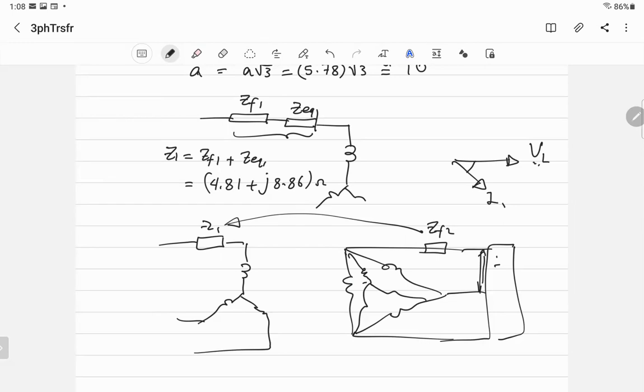Yes, you can take the line voltage and divide by square root of 3 to find the phase, but what about the angle? Is the angle the same? No, there's a shift of 30 degrees, 150 degrees. There are many issues about that. You have the power factor, you have this angle. Usually I make this 0 and it's acceptable, and then let's say 30 degrees, I will have 30 degrees. But if I move it by the same angle to the other side, there is a mistake and it will give you the wrong answer.